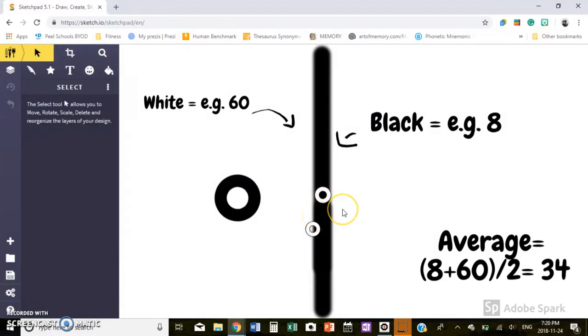But what you should be doing to get the most accurate and the smoothest turns is the closer it's towards this target value, the less of a correction it has to make, and the farther it is, like all the way here or dead center in the black, the sharper of a correction it needs to make.